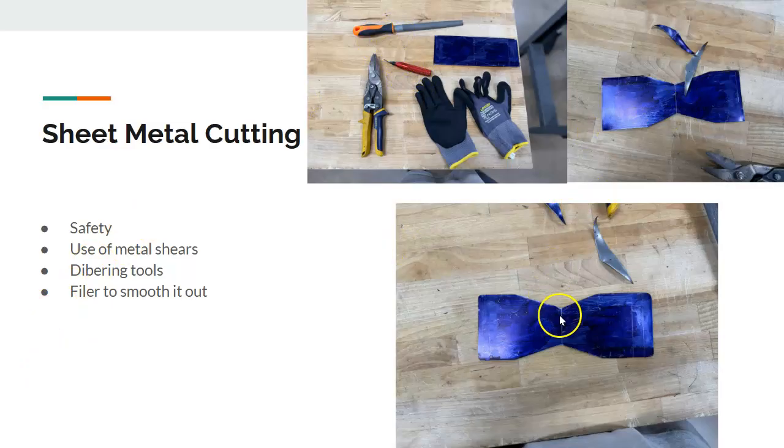We first began with cutting out the middle parts with the shears, in which we just followed the line until we got to the middle point, and we just left a little bit so we could wiggle it off. After that, we used the deburring tool to scrape off any excess metal that would have cut us or hurt us in the future.